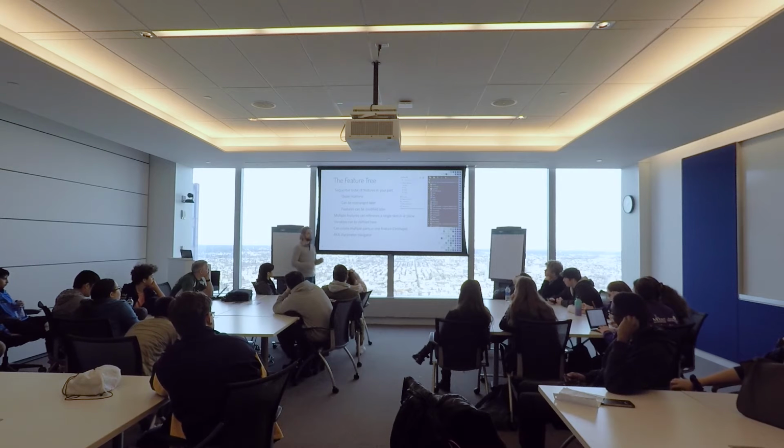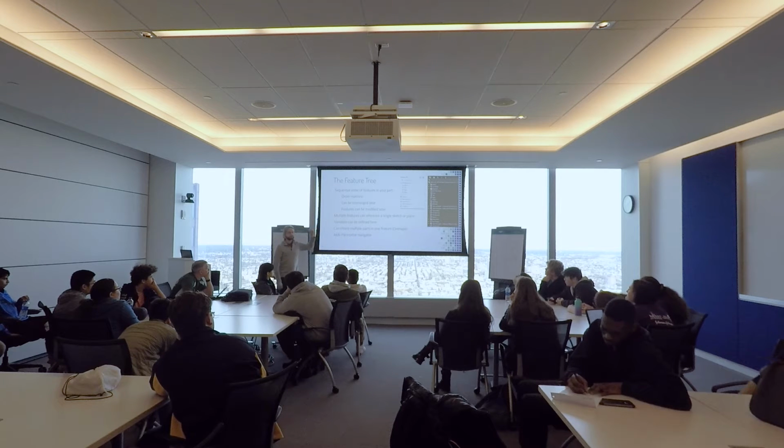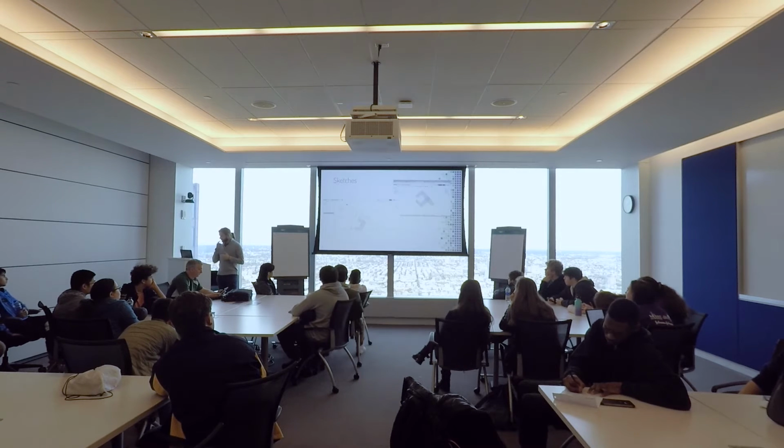So that means in Onshape you have what's called a Part Studio, which is a little bit different. You don't make individual parts. You make all the parts in one place and then import them into an assembly afterwards. And I like to call the feature manager tree the parameter navigator. I think that's a better name for it because it allows you to work around your parameters and see where they are in the grand scheme of things.